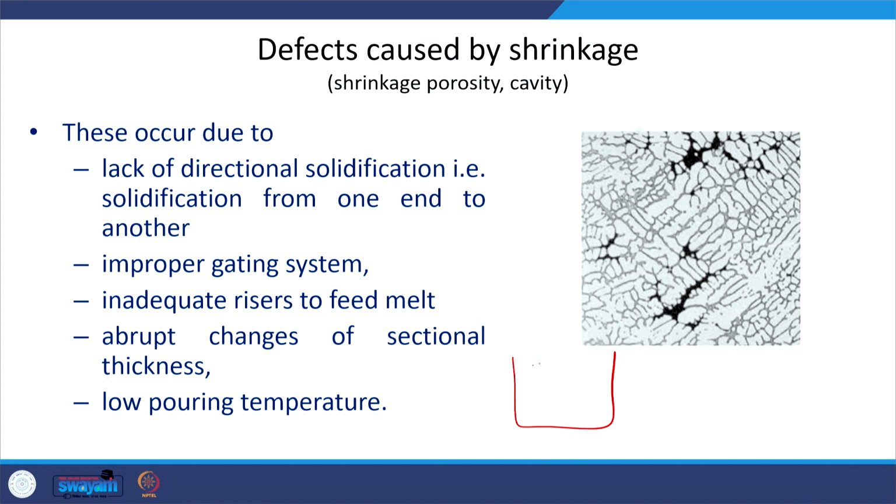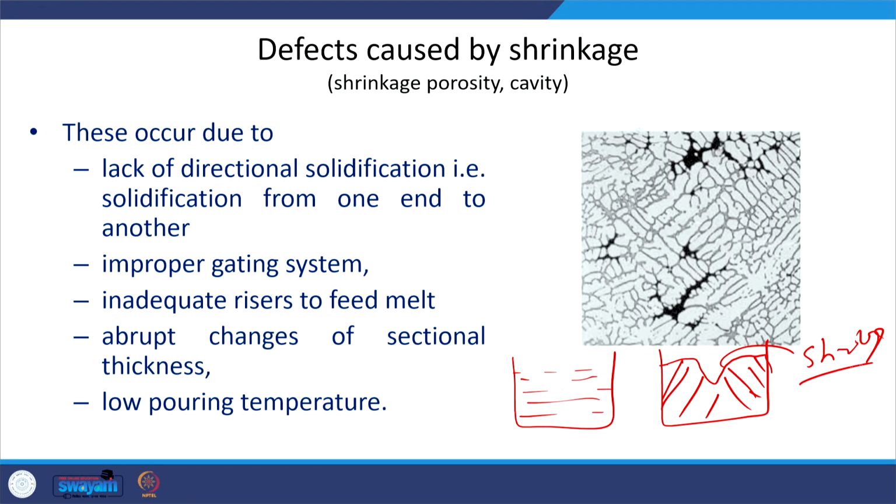Say initially we have filled the molten metal here; on the solidification, what will we get at the top surface? We will get a depression like this in the solidified casting. So, this kind of unfilled section at the top will be observed due to the shrinkage of the molten metal during the transformation from liquid to solid, but this zone which should have been refilled or compensated by the supply of molten metal from the riser could not be, and that leads to this kind of defect.